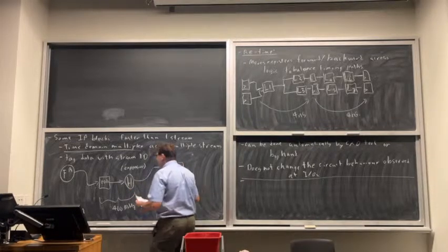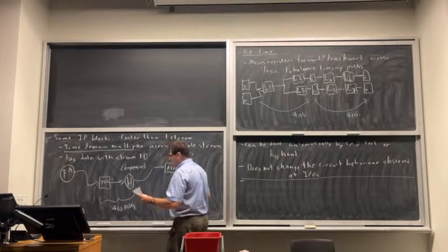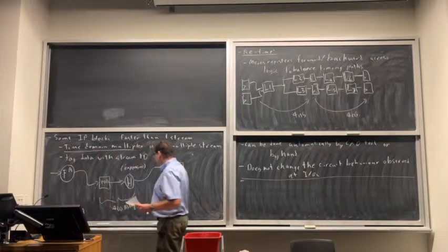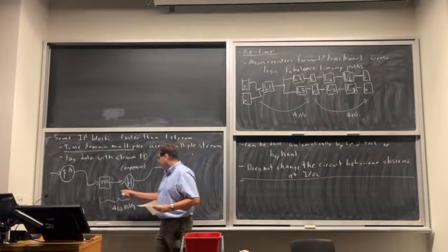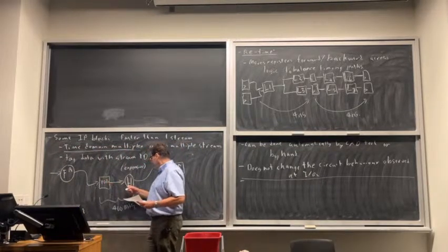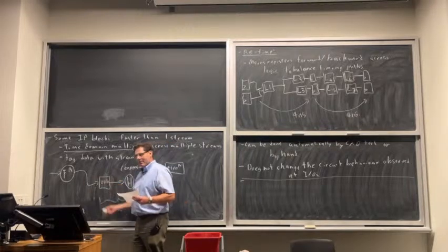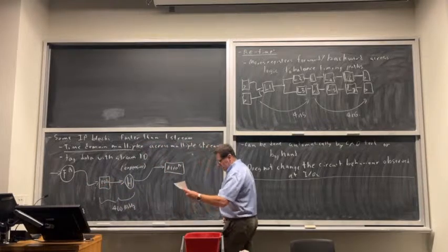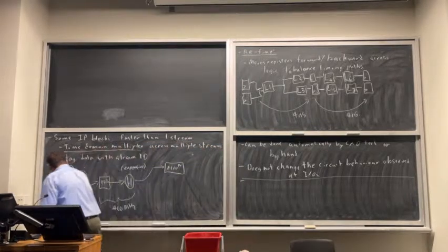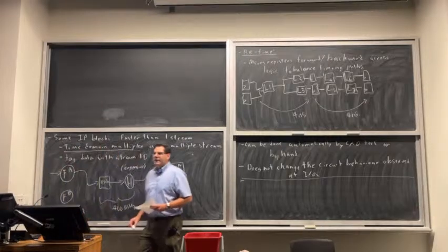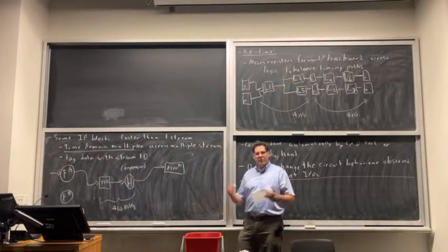Okay, so for my stream A, I'm basically sending a stream of data in. This will work, right? I've got valid bits on here. So this is going to stall every second cycle because it's processing faster than I can feed it data. But if I have another set of work to do, another stream of data, again, FPGAs are often used in signal processing and communications.